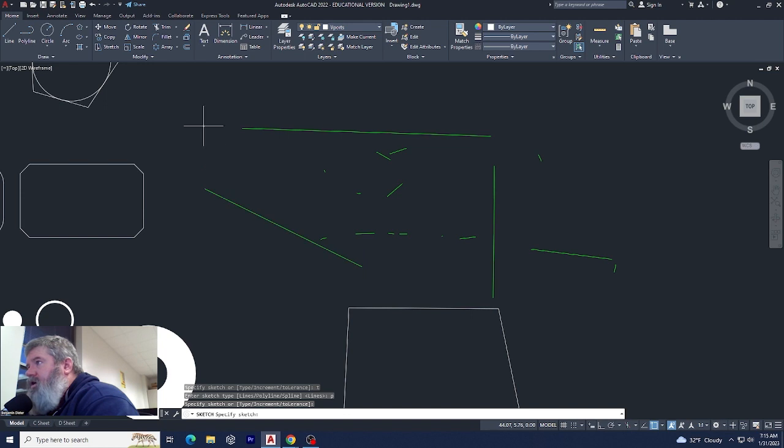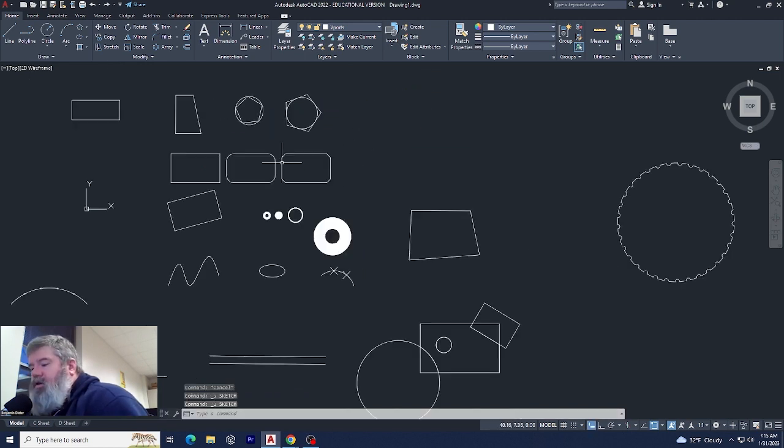All right, so as you see, you click and let go, and it draws these sketch lines. It's one of those commands that I don't really use at all, but I know there's a question about sketch on the test, and it says it's not recommended to use snap or ortho when using sketch lines. That is correct. You do not want to use those. You can choose polylines or splines or different types you want to.